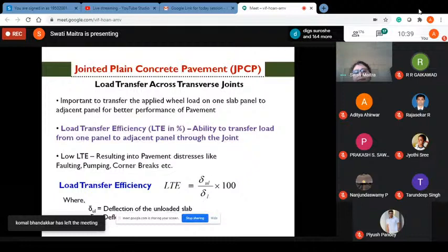Okay, this is the front view. The Winkler foundation is represented, and the brick elements for slab, base, and sub-base are represented like this. And also there is a polythene sheet. It is of almost no thickness, 125 micron, so it is not shown here. Of course, I should have written that a polythene sheet is there, but it has been modeled here, and that takes care of the unbonded interface.